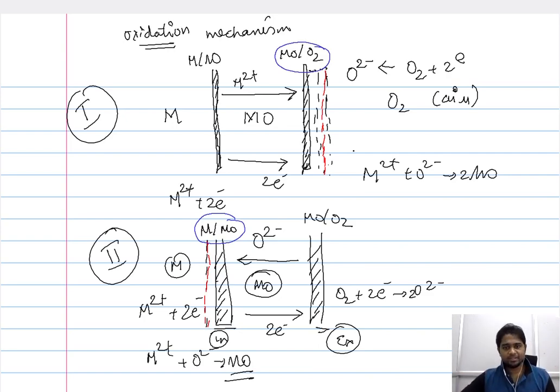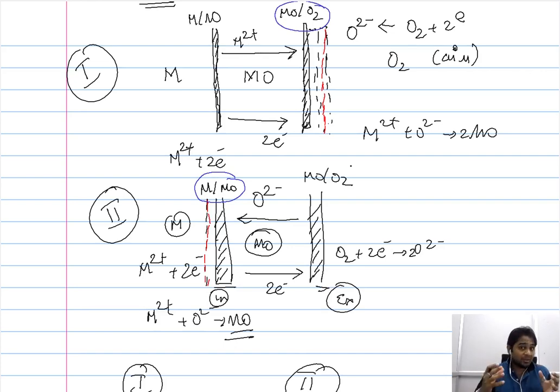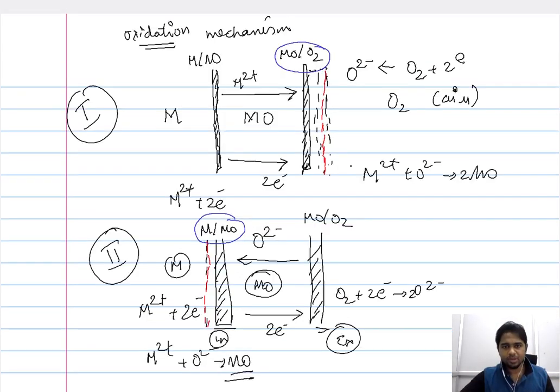The other aspect of how high temperature would influence the oxidation can also be understood by considering the mechanism of oxidation. We have seen that it is possible the newly formed layer, particularly in the case of mechanism 1, can be easily removed as it is formed at the external interface. So this removal is also a form of deterioration, which again depends on the diffusion or the migration of MO. So this migration or deterioration will also be influenced by the temperature.